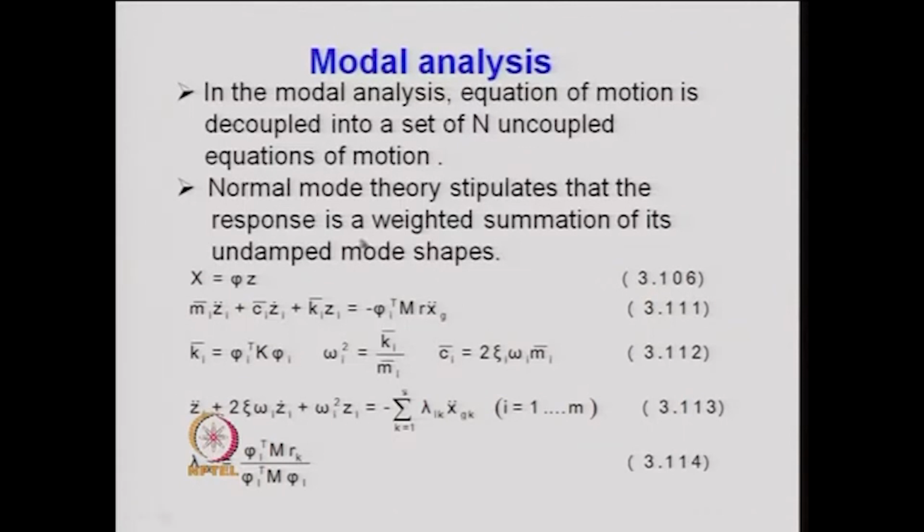So, this is the basis of modal analysis. If we take k bar I and m bar I and divide k bar I by m bar I, then we get the natural frequency square, that is, the ith natural frequency.